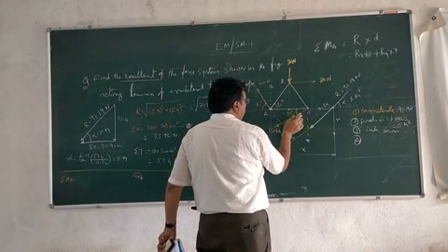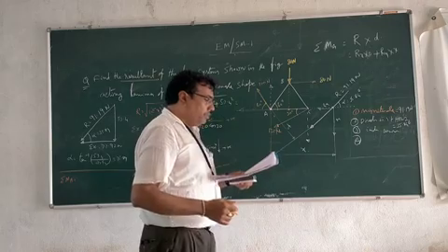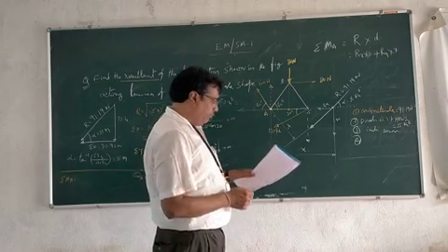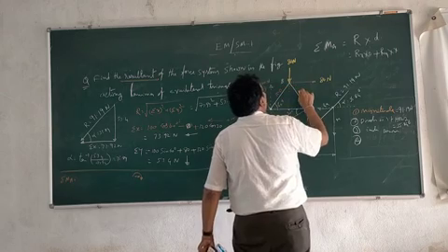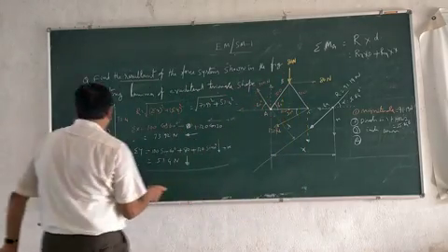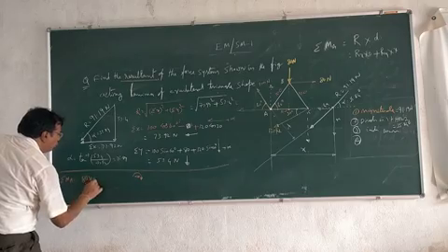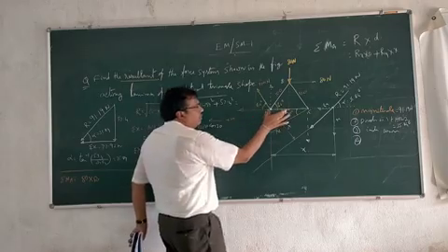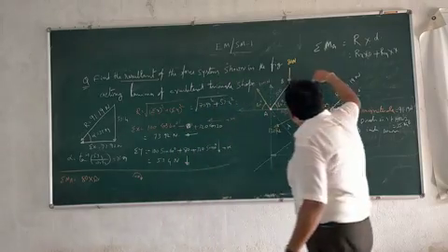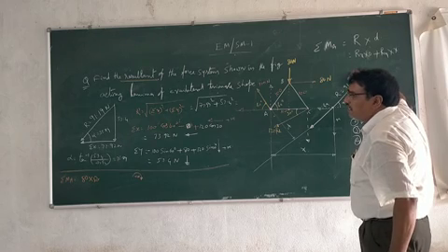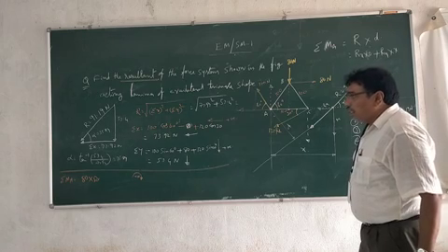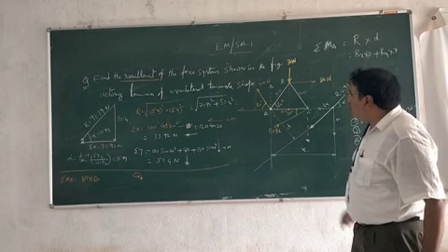That's why. This is the distance. How much is this one? Given the length given here, 100 mm. This is 100. This side, this is the 50. 80 into 50. Moment arm is 50. Force is 80. Next, this one, horizontal force, it is also clockwise. It gives clockwise motion or rotation or effect to the member.